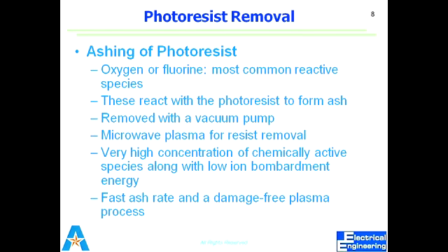When you are talking about dry etching, you should know how the F by C ratio affects it, and you will see that it works differently for silicon and silicon dioxide. Because this is all about the dry etching process, and today we are talking about cleaning, not dry etching, I don't want to get into details. But when you talk about dry etching, you should raise the question about F by C.